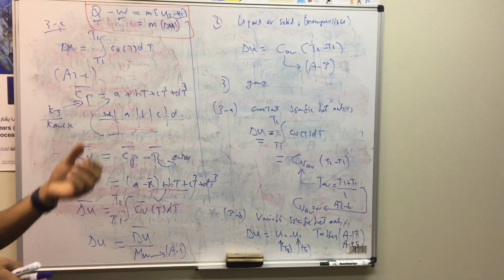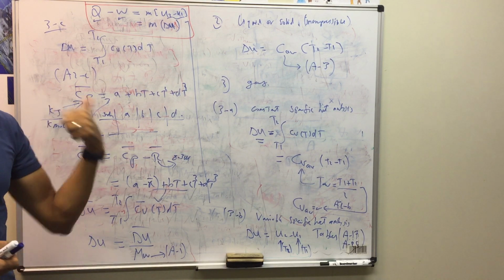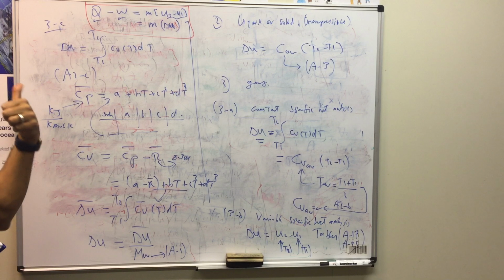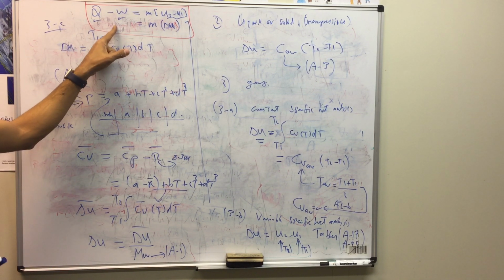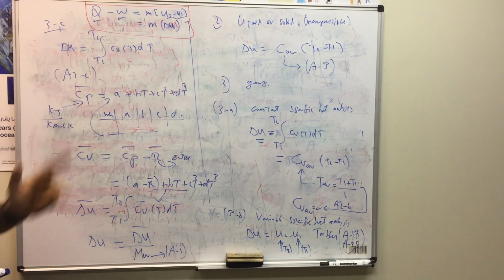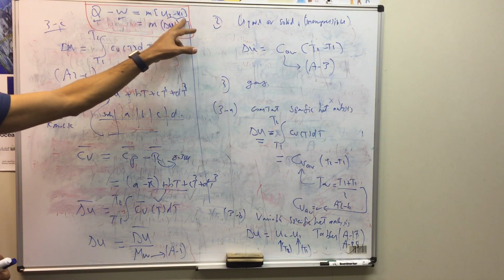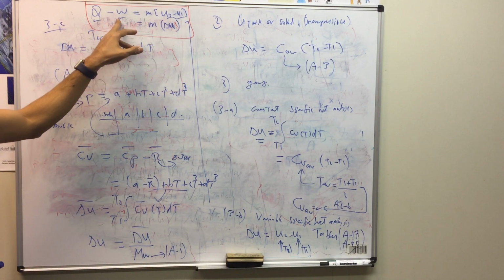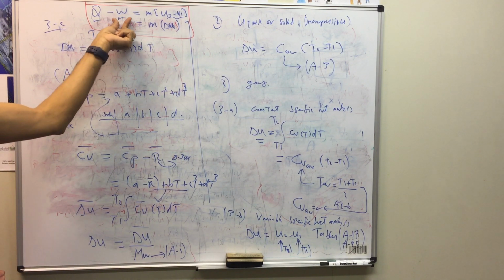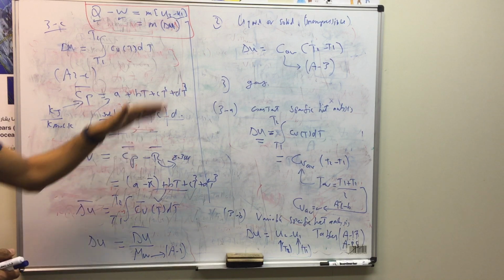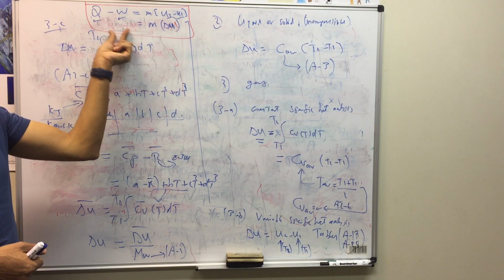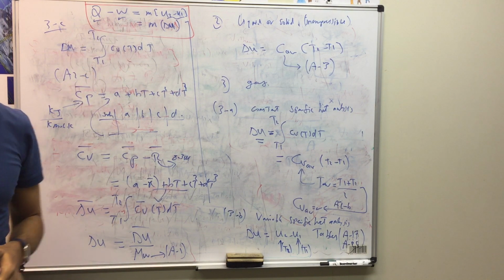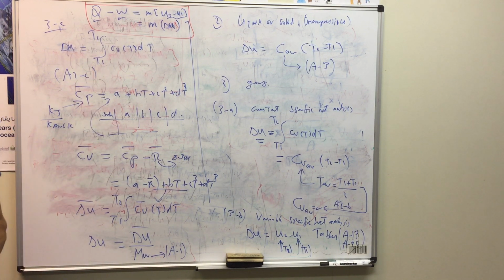So first of all, we have to decide about the system. You have to decide whether the system is a closed system, and then we can apply the first law of thermodynamics. And then you have to decide about the working fluid so that you can calculate the value of delta U. If we do have gas in a piston cylinder device or something, in this case we have to decide about the boundary work, which equation will be used to calculate it. Then we can just apply it in this equation. Usually you need to calculate the heat transfer or the work done, and simply we can do it. That's all about this chapter.